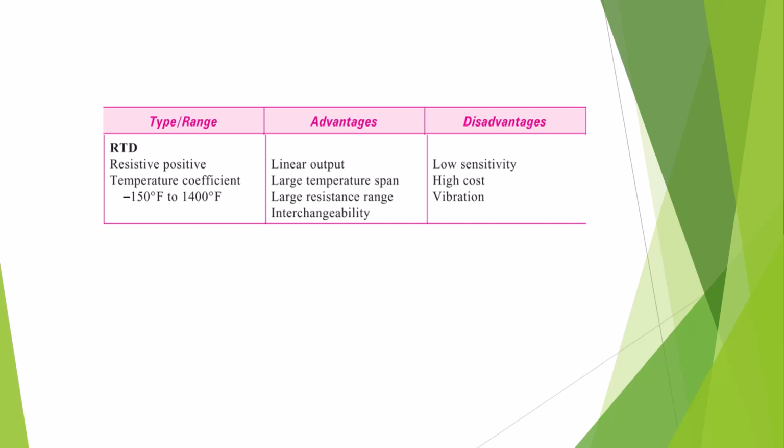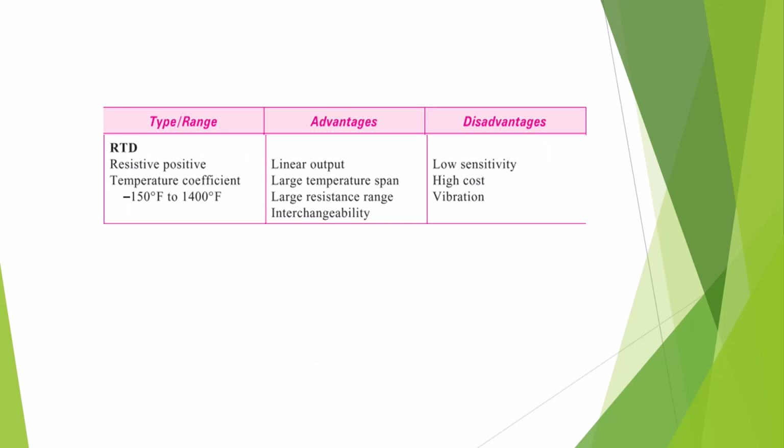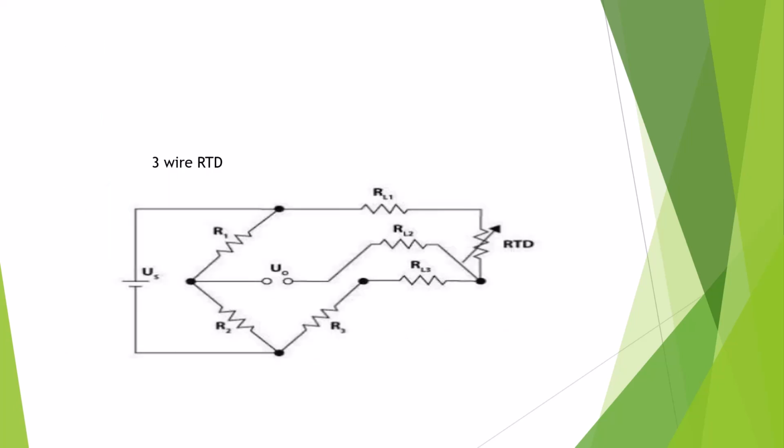RTD's advantages are linear output and very accurate reading. But its disadvantage is low sensitivity, and it is affected by vibration. Sometimes its reading goes up and down. But we know RTD is very popular on site.